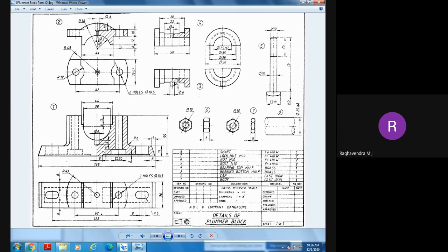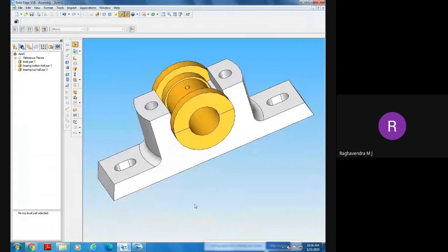And here we should leave a gap. Notice here, it should not fit exactly onto this particular face. The bottom of this cap should not sit on this face because there's some gap, some 6 mm gap. So like that, we need to provide a gap here.